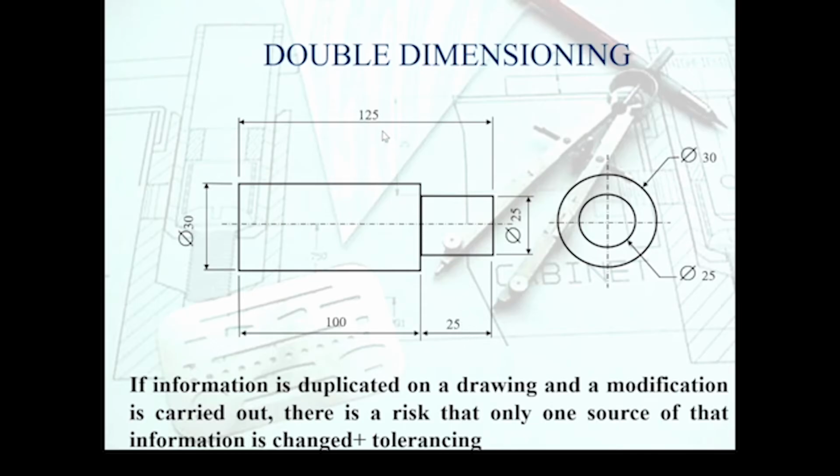However, if you look at the tolerances here, that becomes 124 and 126, which then conflicts with the higher condition and the lower condition on this end, really. And that's also one of the reasons why we must avoid double dimensioning. It is a bit of an acquired process. It takes some thinking about, and also having some manufacturing knowledge, if not manufacturing knowledge directly, probably anticipating how something can be made, definitely helps pick your dimensions wisely.